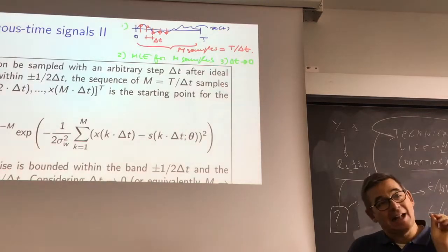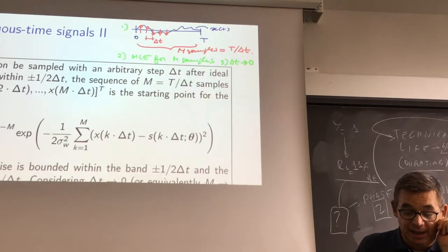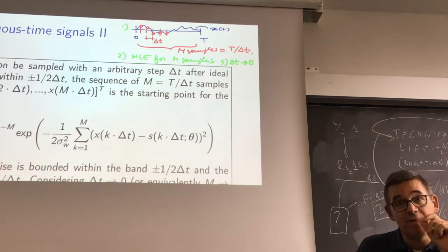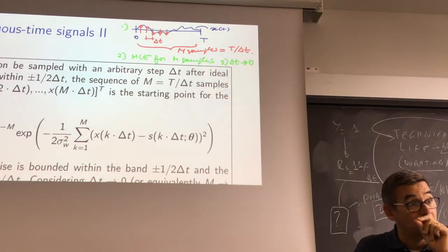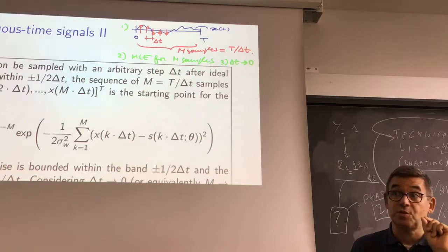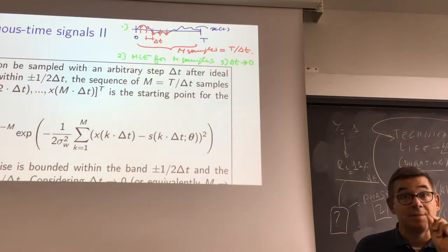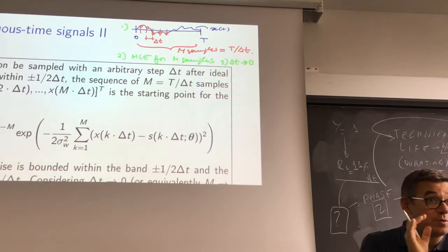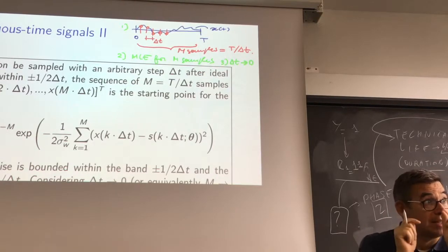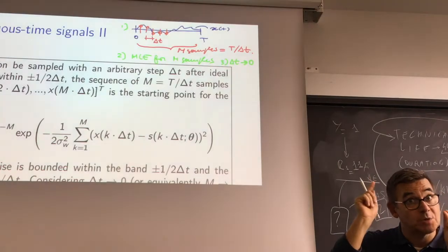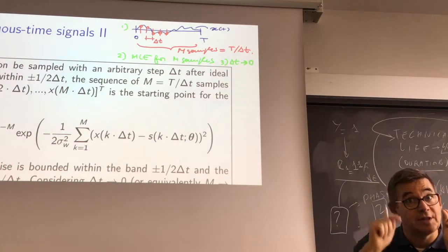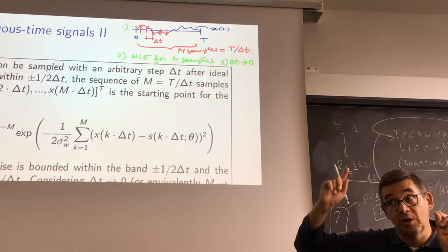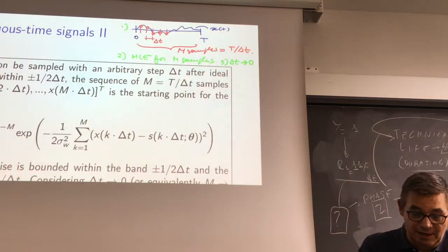Now there is a technicality on that. If I have a power spectral density of N0 divided by 2, the power spectral density for a discrete one should be limited between minus 1/2 times 1 over delta t and plus 1/2 times 1 over delta t.